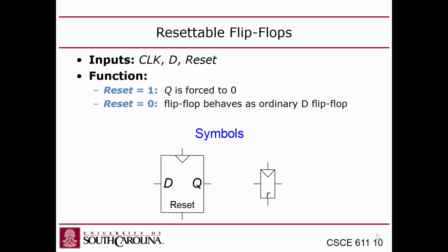So the reset is used to initialize the flip-flops to a predefined initial state. Back when I was in school, we called it the sanity state, meaning that it was a known starting value, and the reset had to actually be pulsed. So you'd fire up your chip, and the first thing you do is pulse a reset signal, which would be connected to every register / flip-flop in the chip.